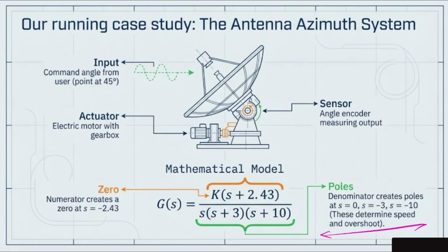It's not just about the gain. We have to talk about the phase delay. That's why when we are talking about gain and phase, we have to work on the Bode plot. So root locus is just about the system itself, while Bode plot is going to read what would happen with different frequencies. So this G(s), which is the normal transfer function, without any compensator, is the mathematical model of output divided by input.